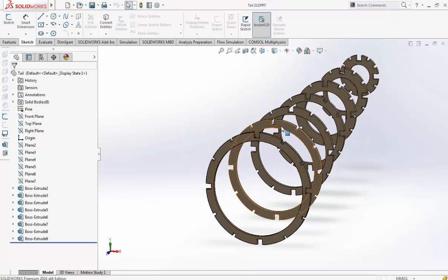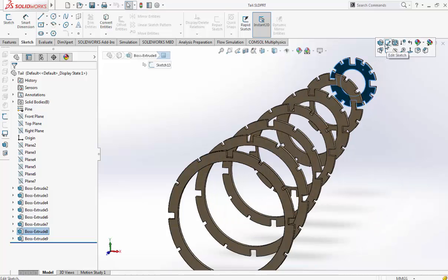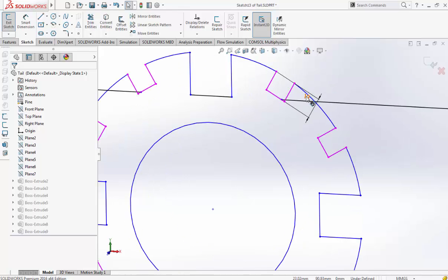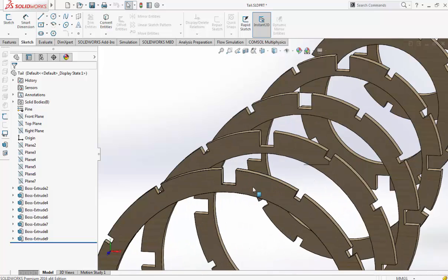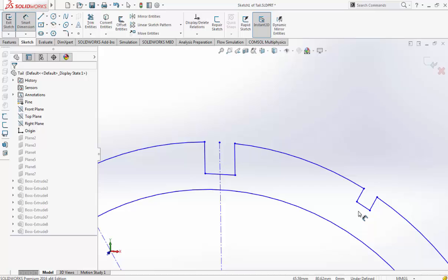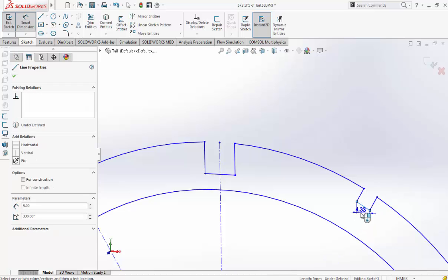Just consider that when you are reducing the diameter of this former, the slots should not change, otherwise you will have a stringer which you cannot build, because it starts from 5 millimeters, and then you have to grind in order to reduce the volume. You can do it, I mean, it's up to you. For example, this is 5 millimeters, and the other is 5, and this is the last former. So if you check this one is 5 and, oh, 4.97. Okay, we will put 5.